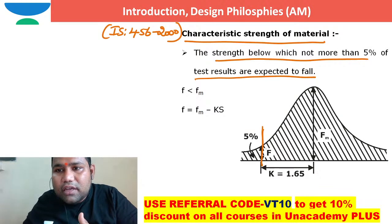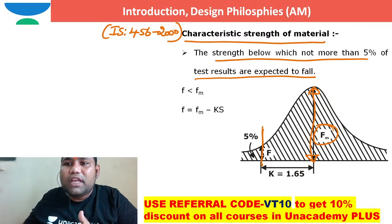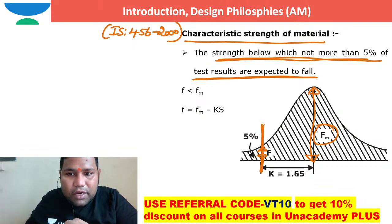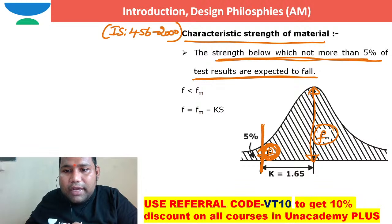The mean strength is the strength at which the probability of failure of the material is 50 percent. Here they are saying the strength below which not more than 5 percent of test results are expected to fail. So at 5 percent probability, I need to find out the strength. The strength at 5 percent probability, we can call it f.